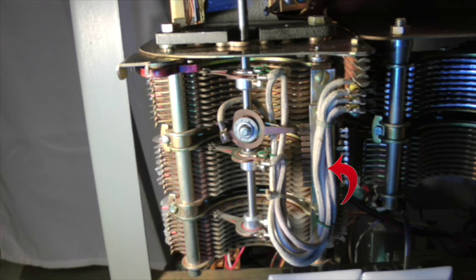The wipers are connected to these flexible wiper cords, which pass the wipers' connectivity through to the line finder relay circuitry. So by controlling the vertical and rotary motions of the shaft, a line finder can access and be electrically connected to the tip ring and sleeve terminals of any of the 200 line circuits connected to its bank assembly.